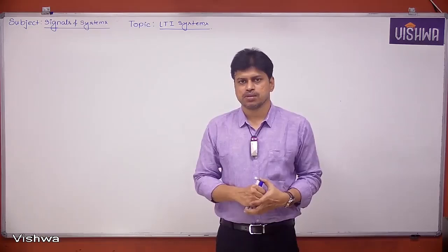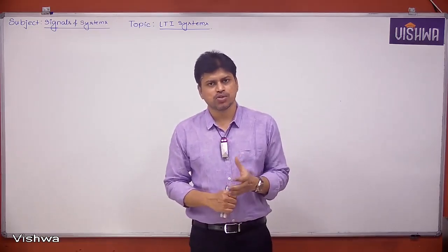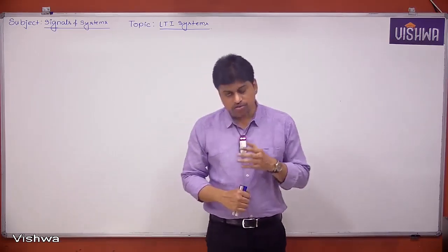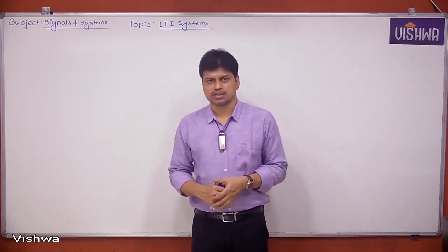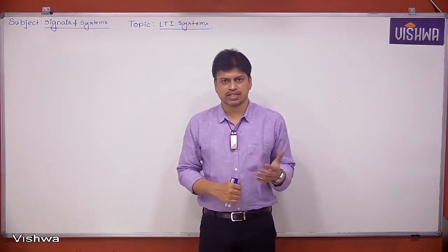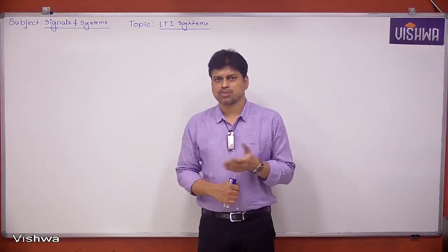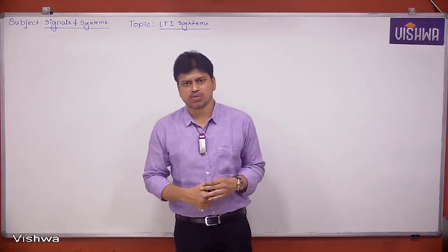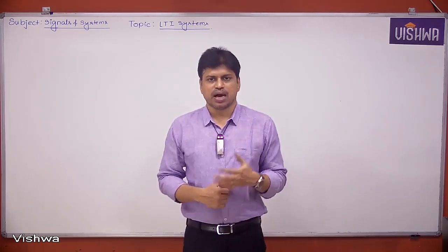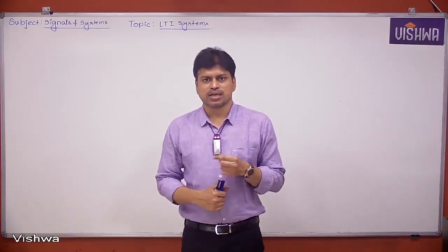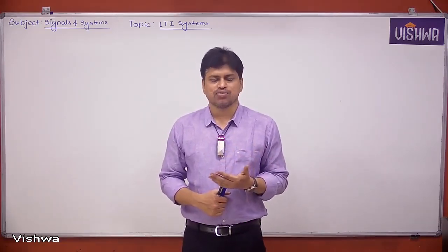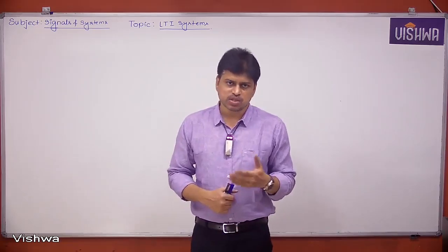Welcome back. In the previous session, we have seen convolution of two rectangular pulses of equal width. I said when convolution of two rectangular pulses occurs, the result is always a triangle. We can find the triangle easily. We just have to see what the lower limit and the upper limit are. Once we know that, we find the midpoint, which is where we get the peak value. We already told you the rising edge and falling edge slopes are equal, equal for the magnitudes multiplication. This is what we have seen.